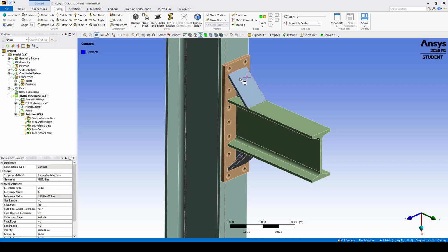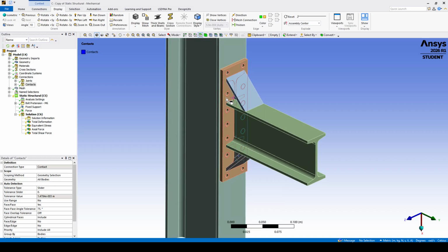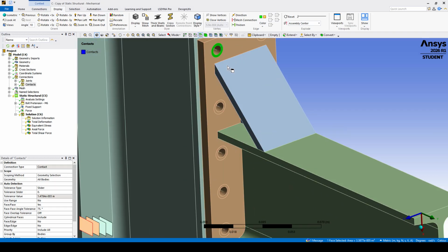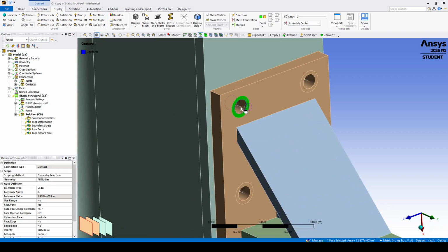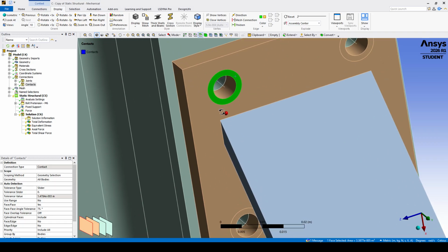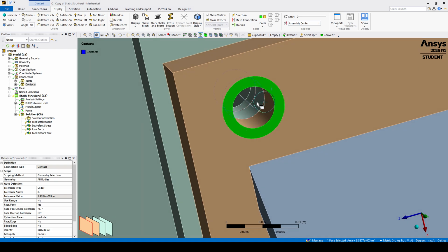This will be effective if you have many bolt sizes in your model. We have to define the vertices, the end point of each beam, in a name selection, and we have to define these faces, which I want to bond the vertices to, to connect my beam to this face, and on the other side to connect these vertices to my thread, which is this face.